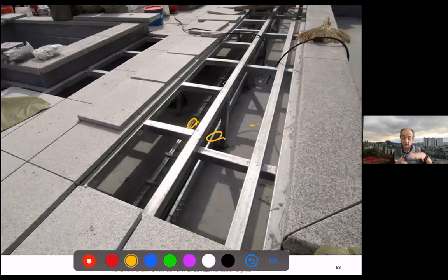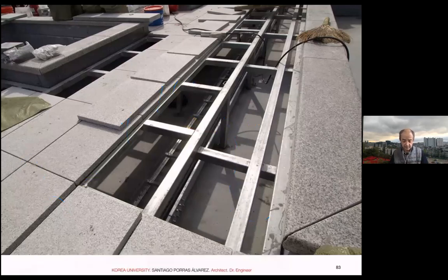And you have enough space to work inside. And you have open joints, so the water can just fall in. And if it needs to evaporate, it's ventilated, so the water evaporates. We do not put silicone there at all. Of course, the slabs are just put on top of the steel. You could have some nice intermediate layer so the stone and the metal are not touching together, but okay, this is how they did it.